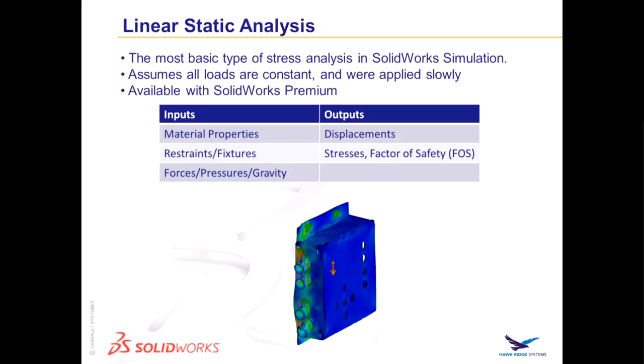And when we typically talk about stress analysis, especially what you're able to use inside SOLIDWORKS Premium, we specifically mean something called linear static analysis. So even though it covers many types of stress analysis, it actually is only going to be valid in specific instances, specific types of loading conditions.